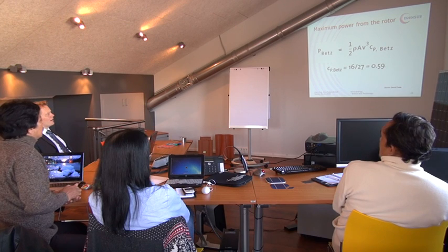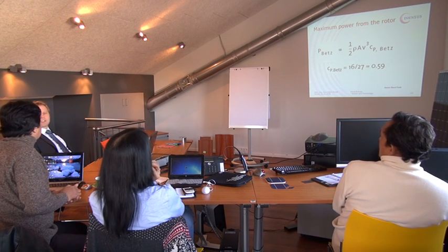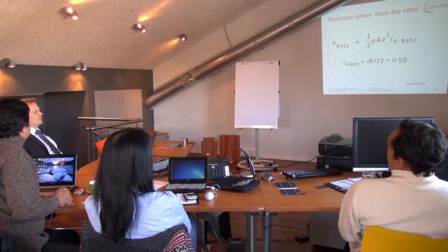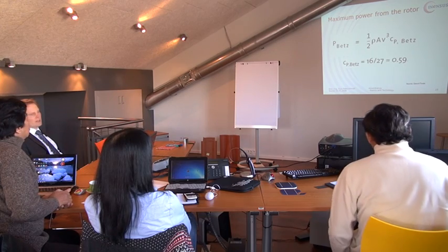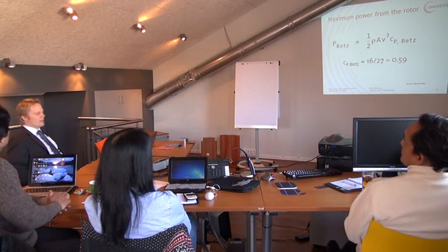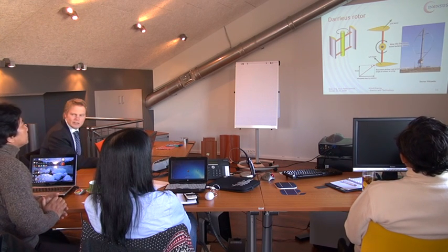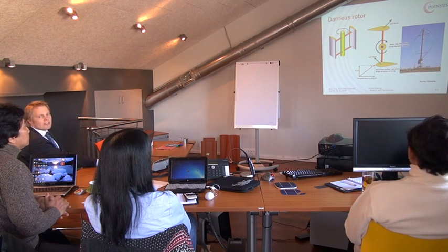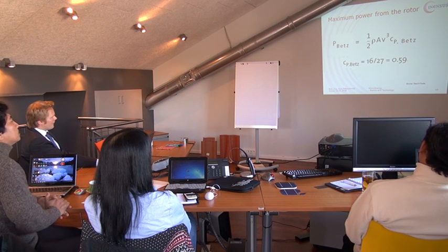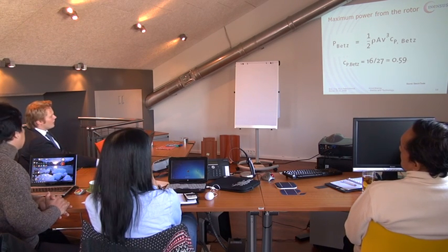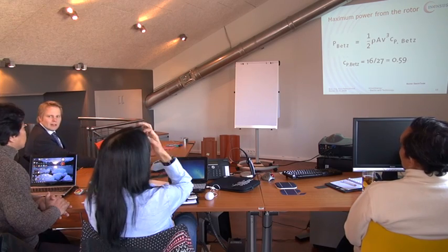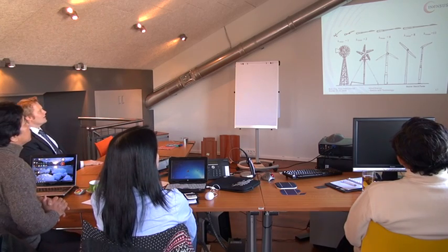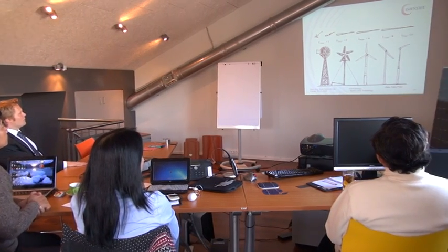The small wind turbine sector has to cope with less efficiency. Smaller rotors usually end up at some 35%, 30%, 25%. If you go for Darrieus rotors, as I just showed, this type up here, they usually have around 20% efficiency. And this is also the reason why they usually cannot really compete with horizontal axis wind turbines. There are different types of rotors.